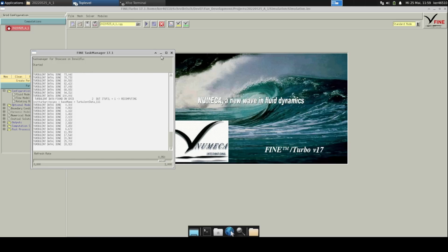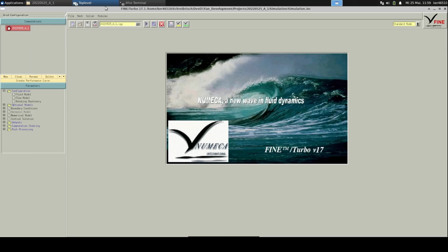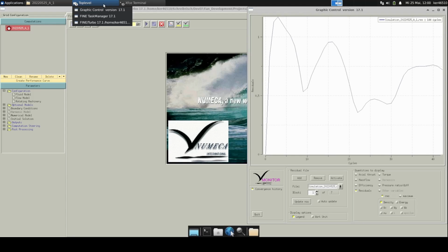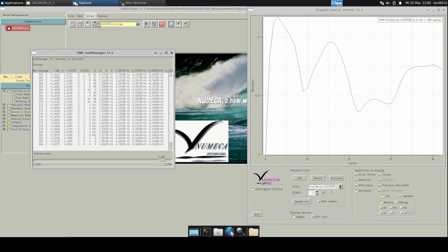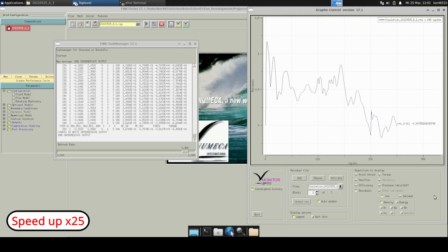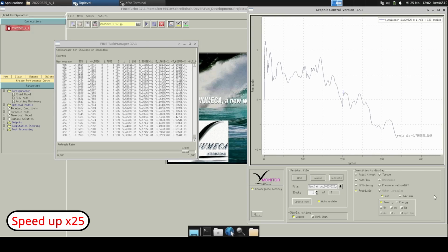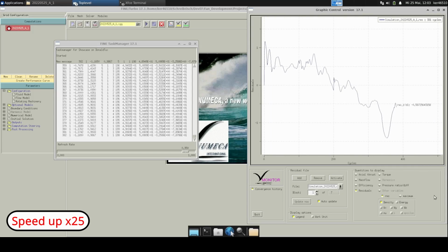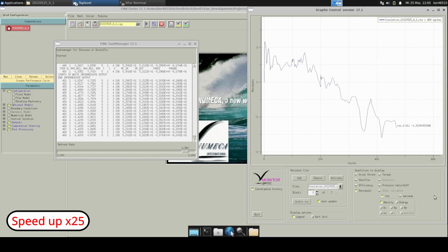Wait until the computation iterations have started in the Task Manager and then open the graphic control monitor. For live data, set the monitor to auto-update. Now you need to wait until the convergence criteria is satisfied or all values have reached a steady state.